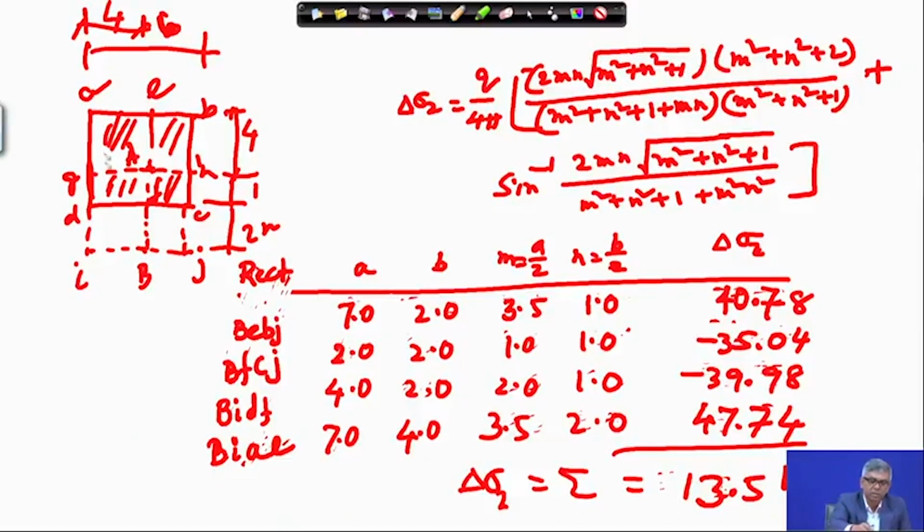So, you can see this is the loaded area. Inside the loaded area, obviously pressure will be more, and when we go away from the loaded area, it will be less. Obviously, we got 137 previously, and when I have gone out of this, it is only 13.5. So, this is another application of how to use the corner formula in different ways, shown in this same problem considering point A and point B.